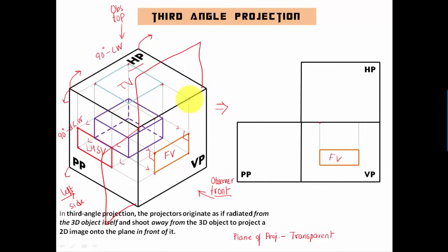Now we have to travel by this much amount from this point over here to this point, and once you do so, you're going to have this point, and you can now go ahead and have the top view. And finally let's have the side view. You're going to have to rotate this by an angle of 45 degrees. I explained the reason why. Then this intersection point gives you the final left hand side view.